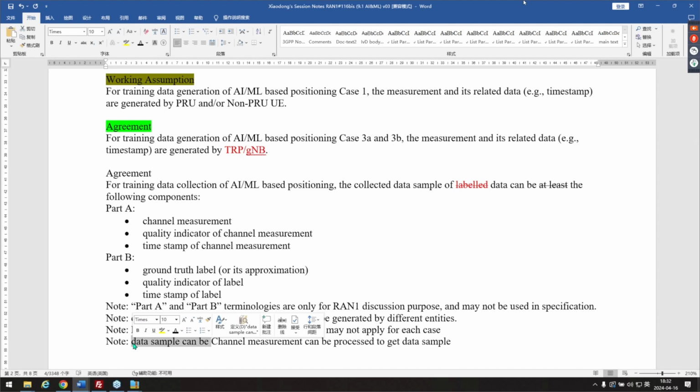In general, channel measurement, we are understanding we are talking about PDP, for example. We know that there is a pre-processing to get PDP, but we understand that this is a channel measurement. We're not talking about raw channel measurement explicitly. But still, the channel measurement can be directly 256 or even 2048 samples you get.